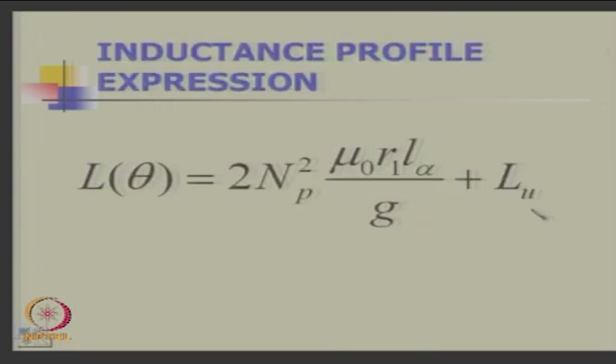You can express L as a function of theta. L is N square into permeance.